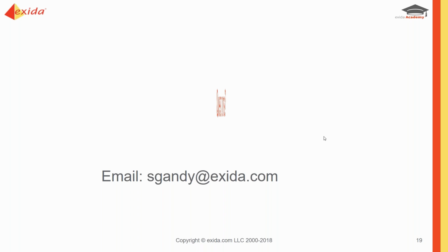Is fire and gas covered under 61511? Well, 61511 talks about safety instrumented functions being either protecting or mitigating. And of course, fire and gas comes under the latter. It's a mitigation system. And you can get certified gas and fire detectors now.